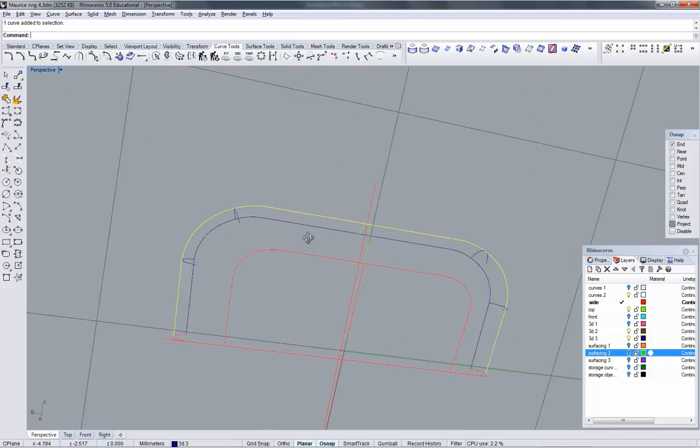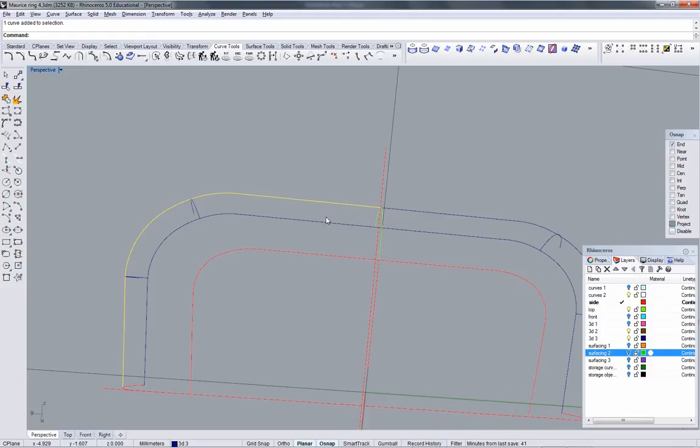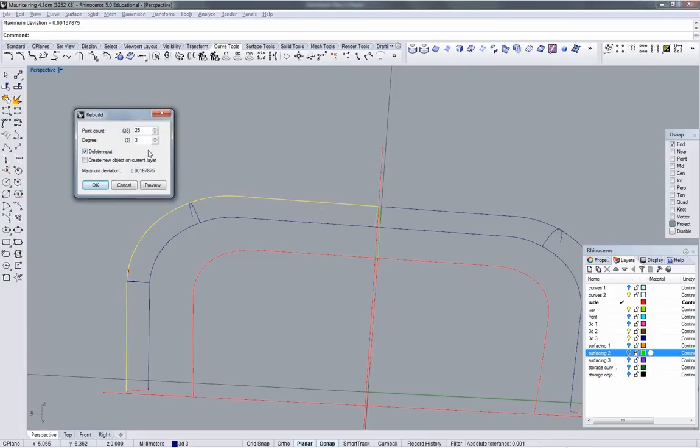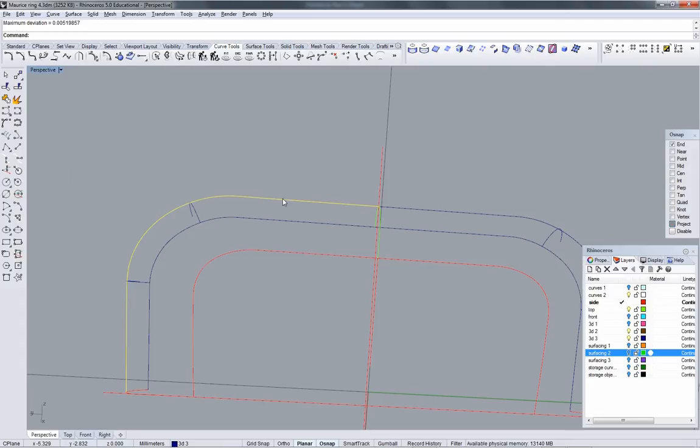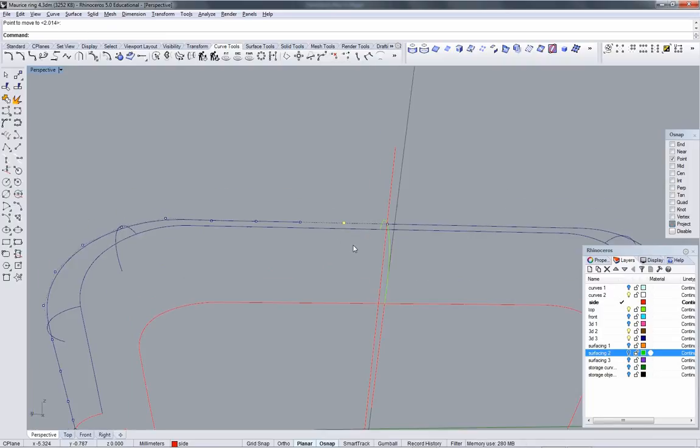I don't love the way this rail looks. I'm going to split it with the center section. I'm going to check the points. It's an awful lot of points. Going to minimize those a bit. Yeah, there are 35 points there. I should be able to define this curve with about 16. Turn those points back on. Actually delete the anchor. And our usual process for keeping a straight line.